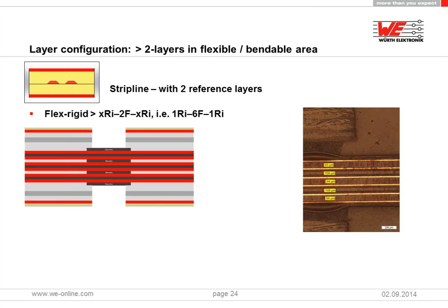Now the next thing is not only to produce impedance-matched PCBs, but also to measure the impedance values with a test coupon. The reason for using test coupons is mainly to have a good contact, repeatable results, and easy interpretation.